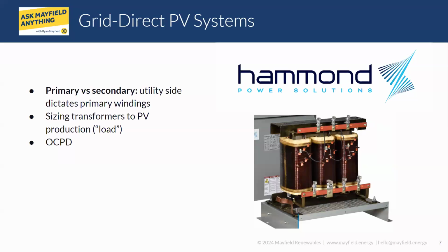Sure. So all of our transformers are suitable and rated for 100% continuous duty. So generally speaking, you don't have to put in a buffer to the transformer. Oftentimes, what buffer happens is the next standard size up transformer, say a 100 kilowatt array, you could go to the next standard size up of 112.5 kVA. Most times, you will have off times where the array isn't producing maximum power or maybe it's nighttime, and the transformer is more than suitable again for that 100% continuous duty.